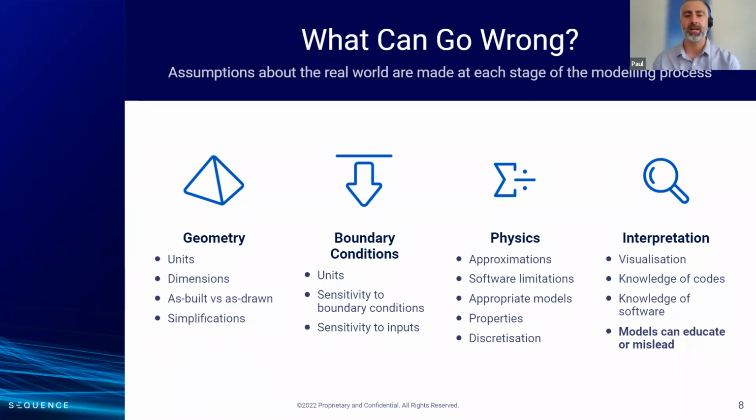And often, if you find you're in a situation where it makes a big difference, you're really left with no other choice but to extend the extent of your model, maybe include something like contact between the various parts that are in your model, support the model in a different way. So that's a really important thing to be aware of as you're moving forward.